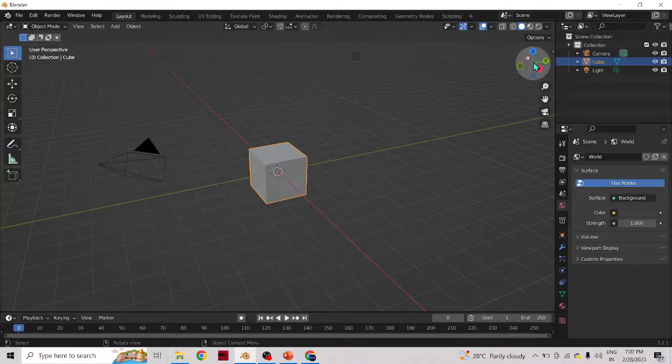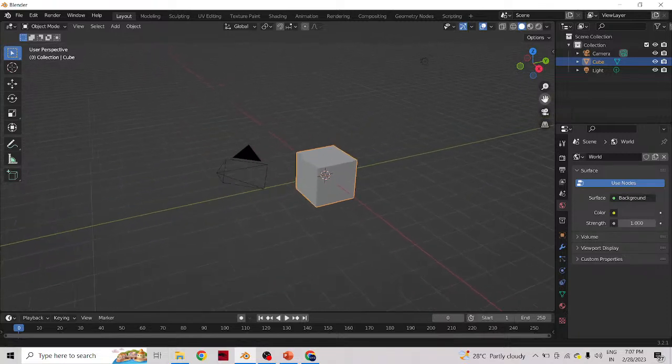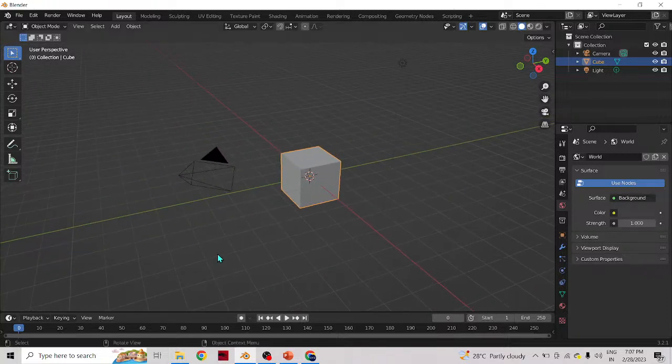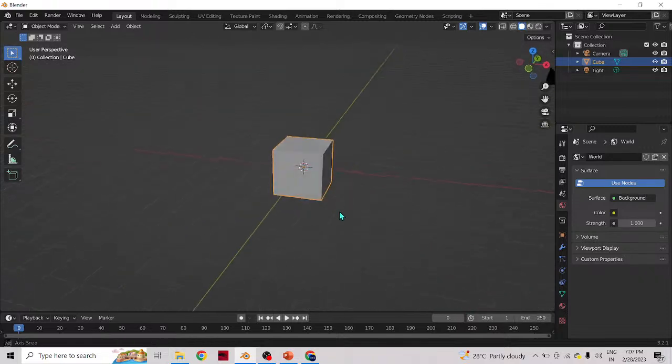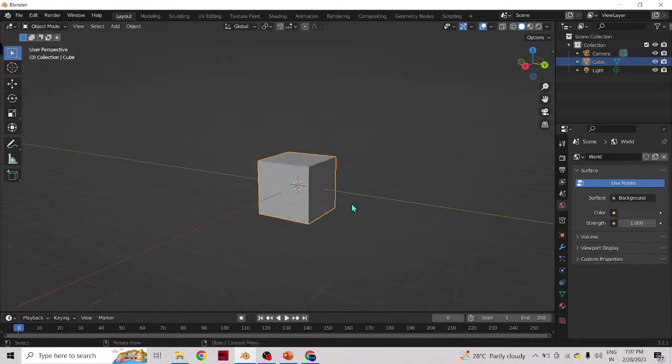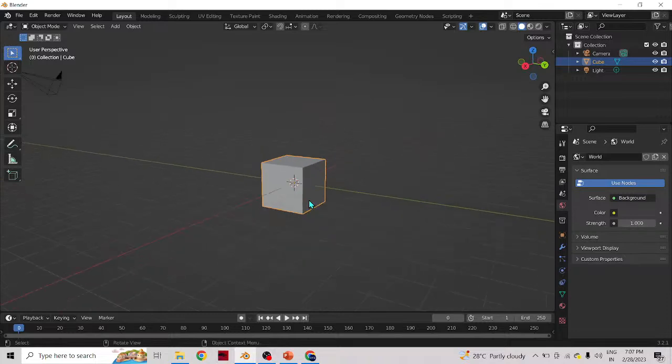Okay, so there we saw what the z axis will do and what the x, y, and z axes are. So next to it, we also went through the move tool which is over here, and also we got to see different options for panning the viewport, toggling the viewport, and also zooming in and zooming out of the elements.